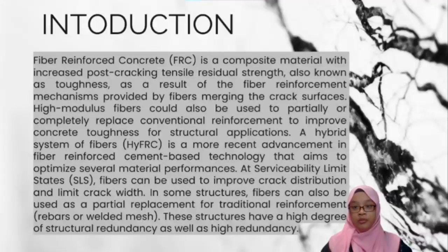High modulus fiber can also be used to partially or completely replace conventional reinforcement to improve concrete toughness for structural application. Other types of fiber, typically with a low modulus and a small size, can be used to decrease shrinkage cracking and improve fire resistance.